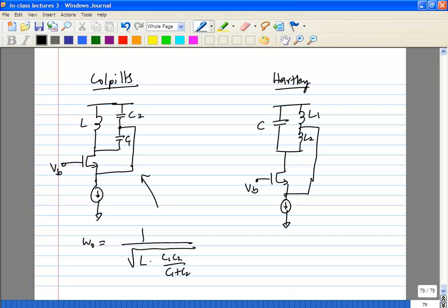Okay. So we know that the oscillator is a large signal system, because the oscillation amplitude is going to be in probably several hundreds of millivolts to probably a volt, and could be higher. So what we'll do first is we'll find out the large signal transconductance of the transistor, in something similar to Colpitts in an oscillator configuration. Then we'll use that in the Colpitts and find out what the circuit looks like and so on.